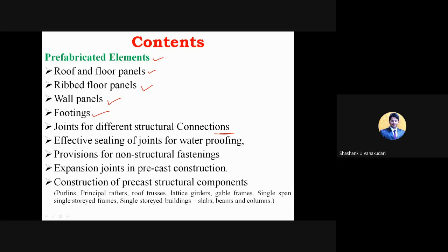Next, effective sealing of joints for waterproofing. Not only for waterproofing, but also for the reduction of stresses, we provide effective sealing of the joints. Once you connect two different structural members, it forms certain gaps between them, right? We need to seal those with different adhesive materials, so that it reduces leakages and crack development, and we can even increase the durability